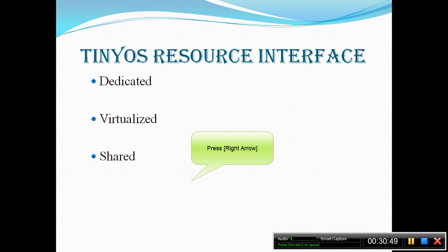Here, the arbiter determines which client has access to the resource at which time. While a client holds a resource, it has complete and unfettered control. Arbiters assume that clients are cooperative, only acquiring the resource when needed and holding onto it no longer than necessary. Clients explicitly release the resources.